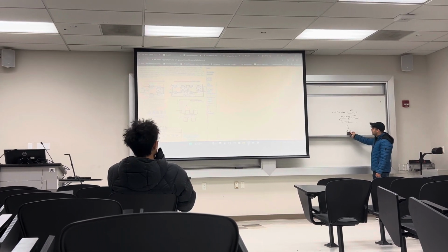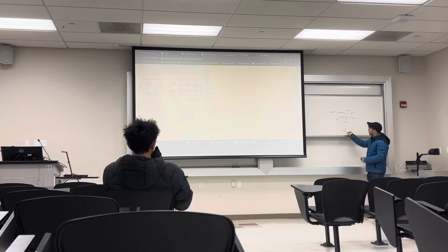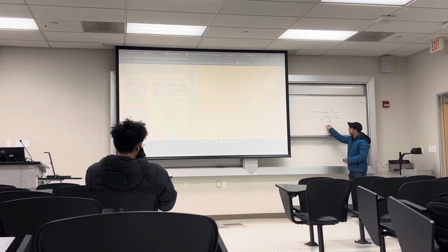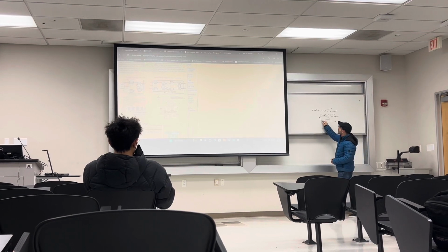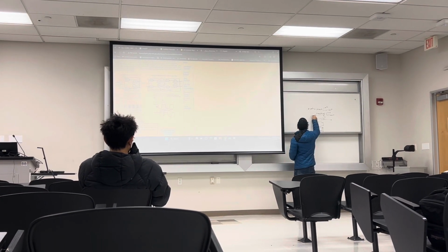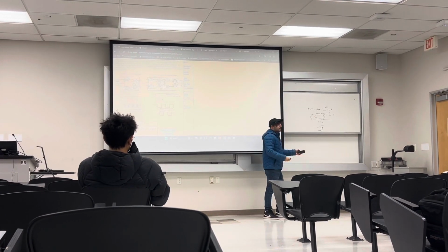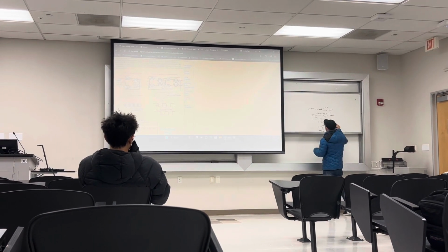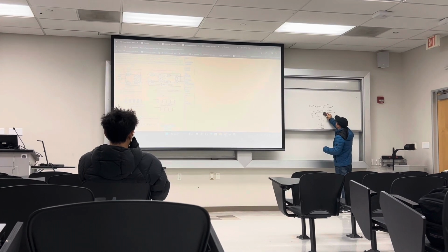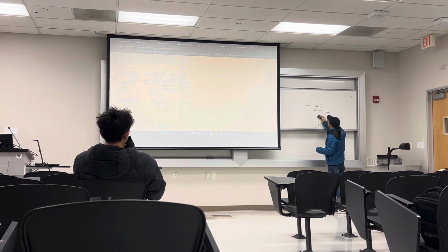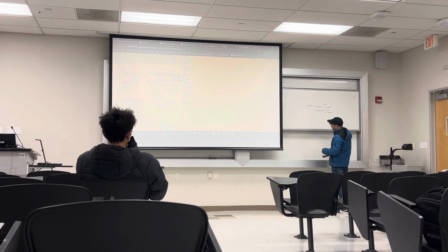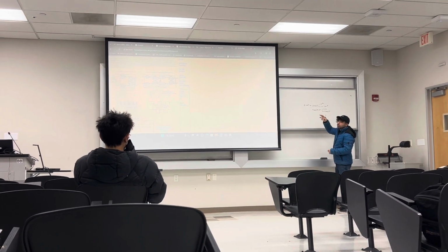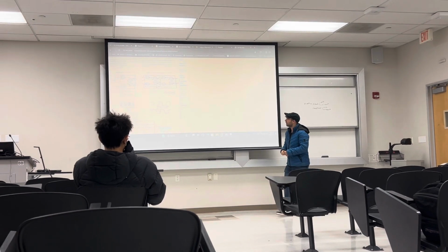The only difference is that you add 1 NMOS here, going to input C, for example, this is B, this is A. And 1 PMOS here, in parallel to the circuit. So you add 1 transistor on the PMOS side and 1 transistor on the NMOS side, and you have a NAND gate with 3 inputs. That's it, it's very easy. From now, you don't need to redesign the circuit like the NAND. For a 3-input NAND, add 2 transistors, 1 PMOS and 1 NMOS.